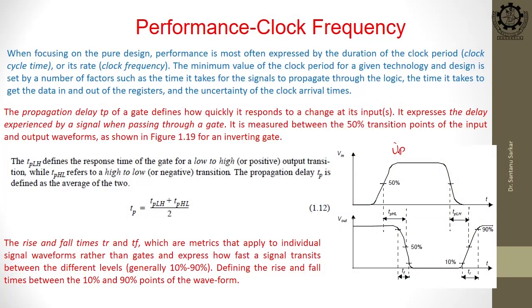These are a few performance measures, how we define the performance, like the clock high to low, low to high. When we have an input signal and output signal, we generally define the delay from the 50% value. We need some reference point, right. What is the delay of this inverter?